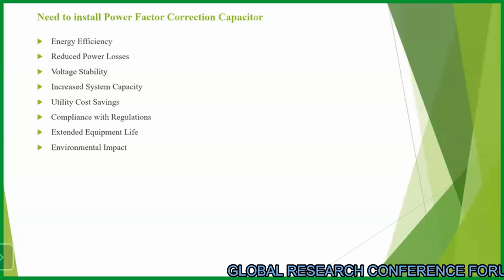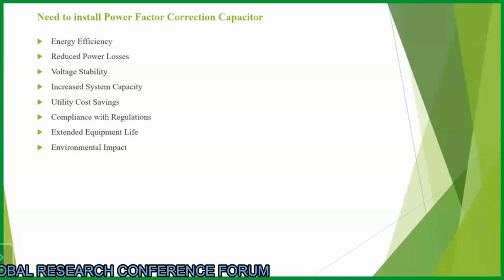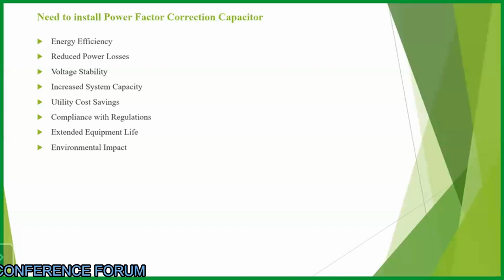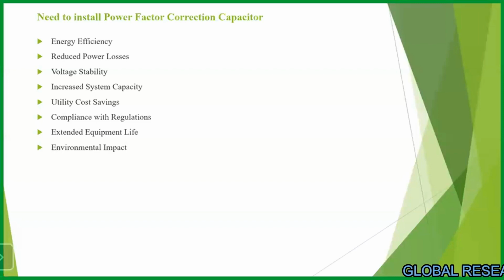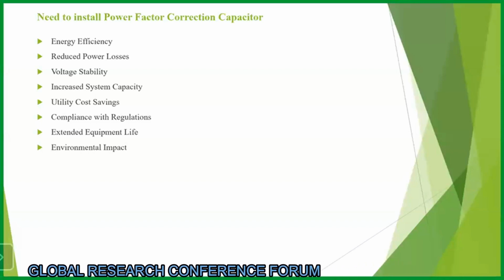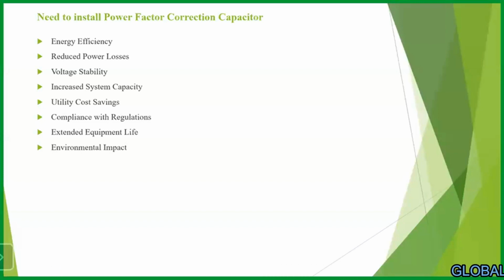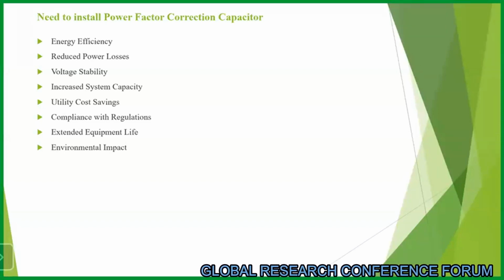In industrial loads, there are always high-rated motors, and motors contain inductive load, so the power factor becomes lagging. To avoid this wastage of power, a compensating reactive load is connected. How the industry gets economic benefits is explained in my presentation. And these are the points.